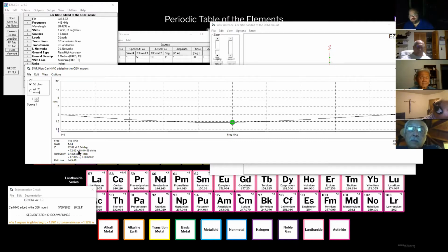And you guys will remember when you were studying, when we're looking at impedance on the Cartesian axis, and they tried to make sense of that. This is where that starts to come into play. But don't get lost in that. Really, when you're just playing with this stuff the first time, you're just looking at this curve and saying, okay, does it match? Yes, no. And then once you're a little bit more comfortable, you're going to start looking like, okay, I'm in the right resonant window, but what can I do to lower this SWR further? And that's where you're going to start to rely on these numbers.